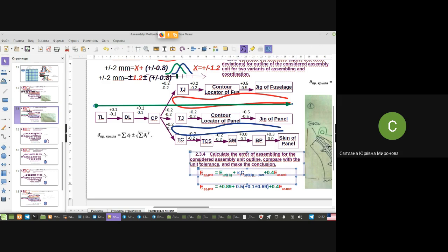And we have the so-called coefficient of fixation. The coefficient of fixation is given in your laboratory manual, and these things that you can't see on your own, you may only read about, and you may know from us. When we assemble something in a jig, in our very first lab, we usually do an experiment measuring with indicators the accuracy of assembling depending on how many clamps you have. And of course, to see the tendency, it's necessary to measure some hundreds of points.